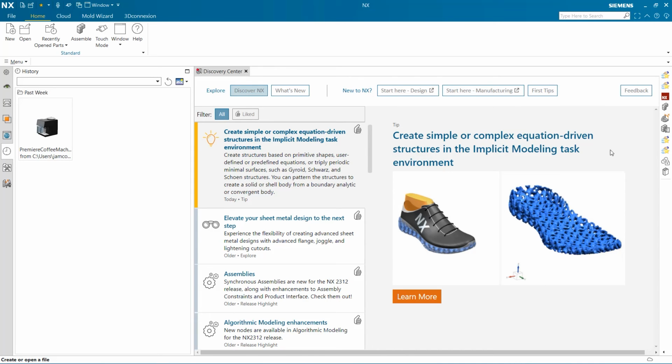In conclusion, in this video, we've discussed two different ways to make sure NX is completely up to date. The first place we looked was in Siemens Software Center, where we saw the option to update our install to the latest version. And finally, after that, we discussed how to turn on notifications and set up our systems to download new installs automatically, rather than using traditional manual downloads.